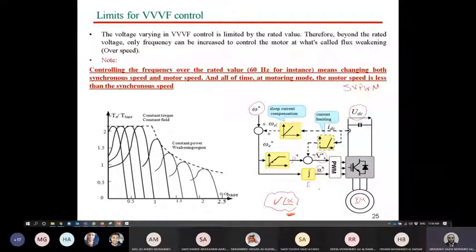It's based on something called space vector pulse width modulation, and it's used for all of the machine types now of control, like field-oriented control, like direct torque control, like model predictive control. And these are the most well-known techniques used even in industry or still in investigation and research steps. Field-oriented and direct torque are used now in industry. However, model predictive control is still under investigation. No company has used model predictive control yet. It's still in research stage.